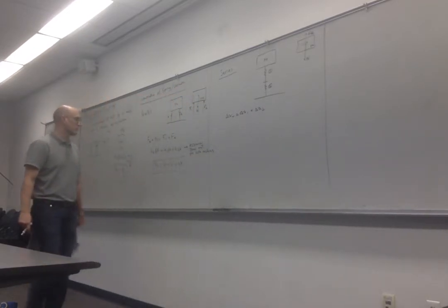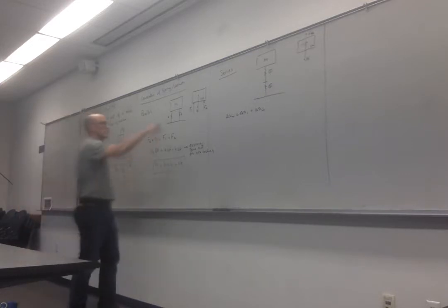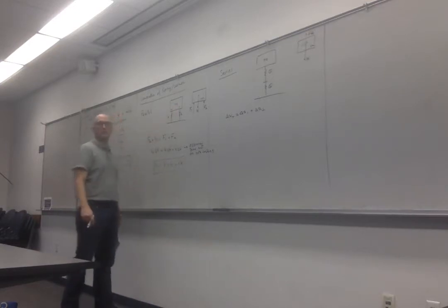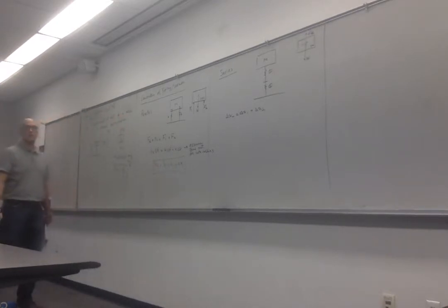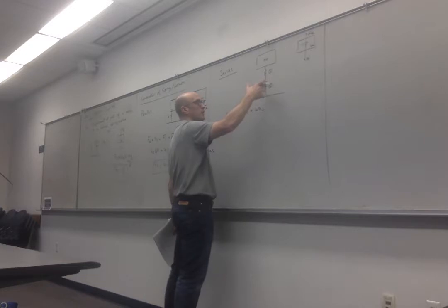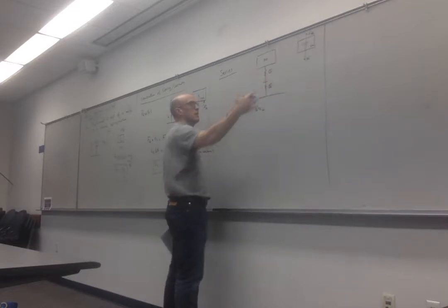Yes? What's the delta X on the parallel one? Where's that in the diagram? It's just a deflection from the spring. Oh, because it goes back to equilibrium, you're saying? So basically, when you put the mass, there's a deflection, right? That would be the small displacement that the mass causes to the spring. Okay? So in here, when you put the mass on, you're going to have the weight that exerts the force on the spring, and since they are in series, their displacement will be different if they have different spring constants, which is usually the case.